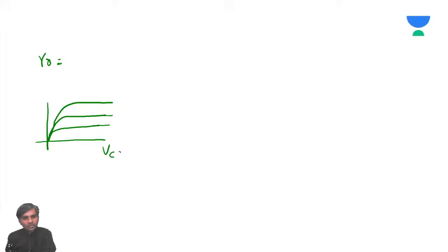So what are the output characteristics? You are going to have VCE, common emitter, right? What is the output voltage, sir, for common emitter? VCE only. And what is the output current? IC current. So now what do I need, sir? I need resistance. R is going to be V by I. Here R is on the x-axis and I is on the y-axis, so can I call this simply y by x?